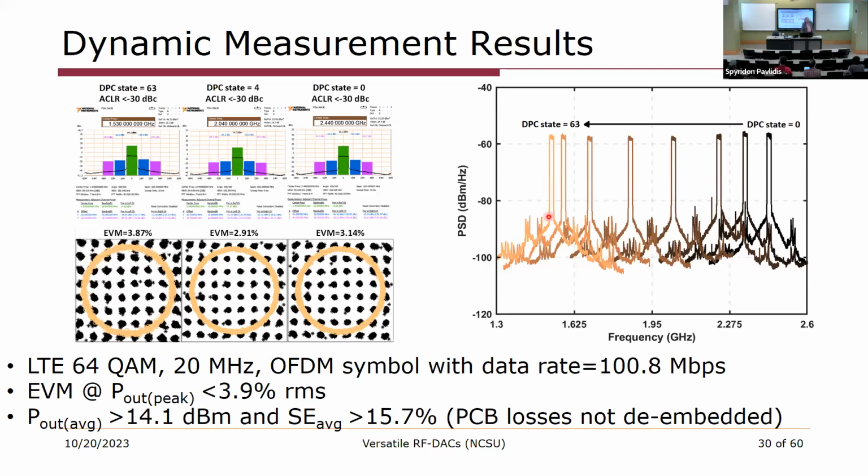One of the nice things that you can see about the tunable narrowband operation is that the out-of-band noise in a digital power amplifier is typically dominated by quantization because this is fundamentally a DAC. Quantization noise is white. But here you can see that the narrowband filtering is actually helping to shape and reduce the quantization noise a bit.